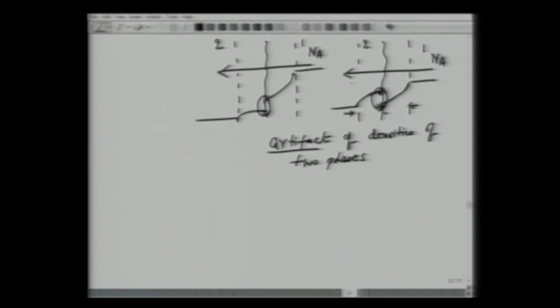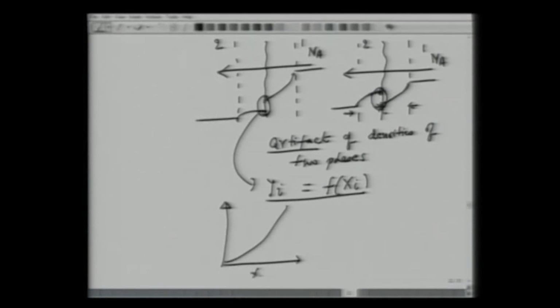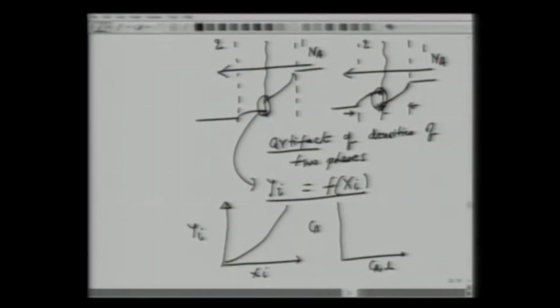That's not important. We are saying that for the interface concentrations yi, there is thermodynamics which says that the two are in equilibrium concentration. So one has done a batch experiment or has some reported data where, knowing xi, we can calculate yi, or knowing CAL we can calculate CAG in the gas phase.